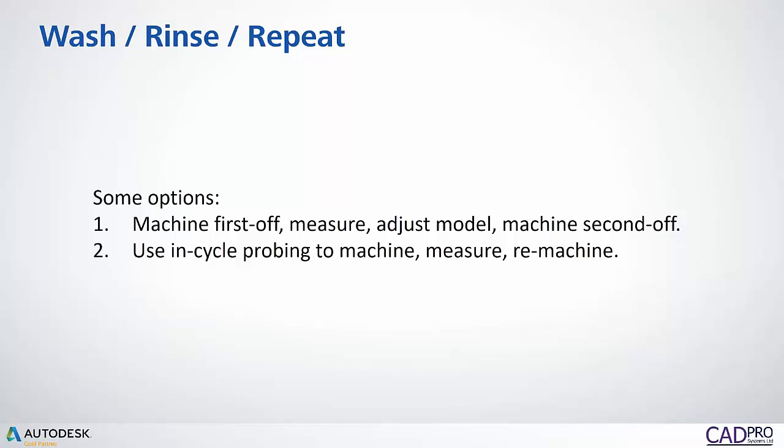So in testing this at one of the events we did recently with one of our customers down here that's got a UMC 750, with this part, after the first pass, the diameter was sitting at 30.036, which is about exactly 0.004 millimeters below the target. I think that's 1.6 tenths, as you guys would call it. As a tenth is a 10,000th of an inch. Is that right?